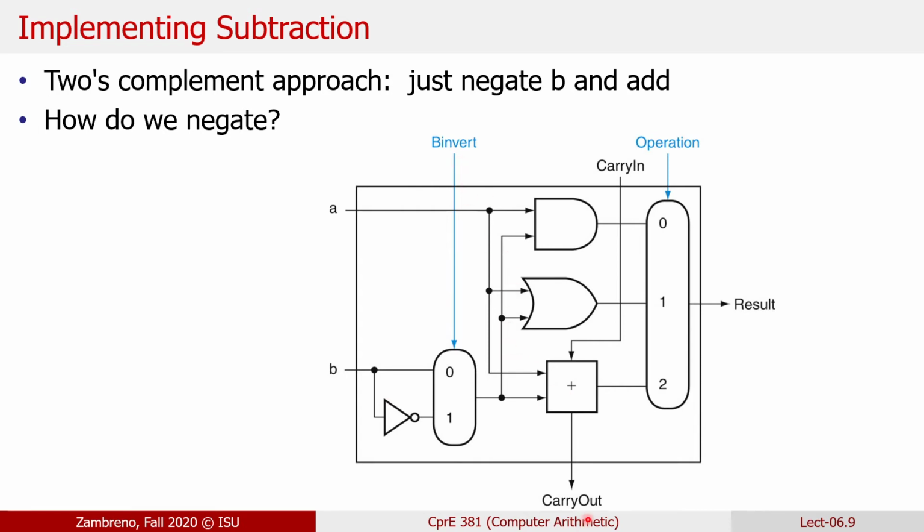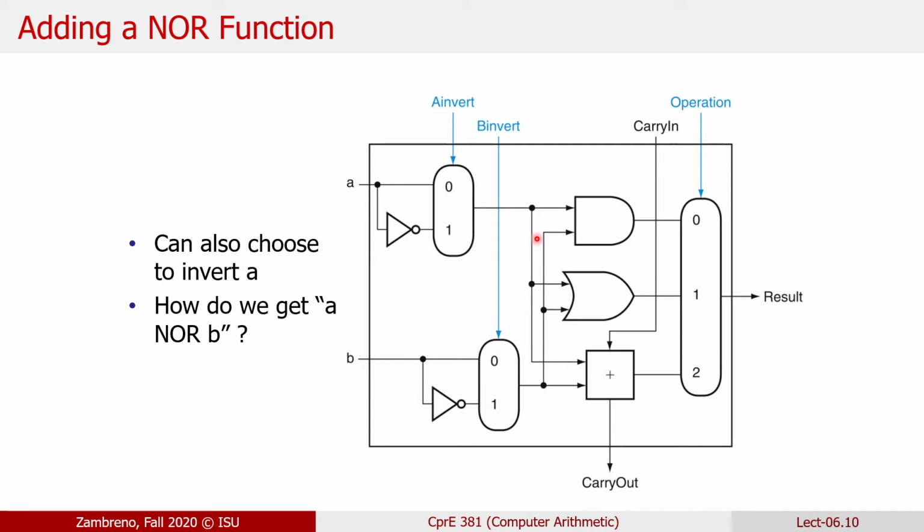And likewise, as we try to get a little bit clever and maybe use De Morgan's law, going back to 281, to get other circuits kind of for free, that scheme is still entirely up to you, and I think that's the nice part about this. Technically, this single bit signal is being used to drive a mux that is selecting between an inverted value of B or not, and we likewise now would have one potentially for inverting A or not.